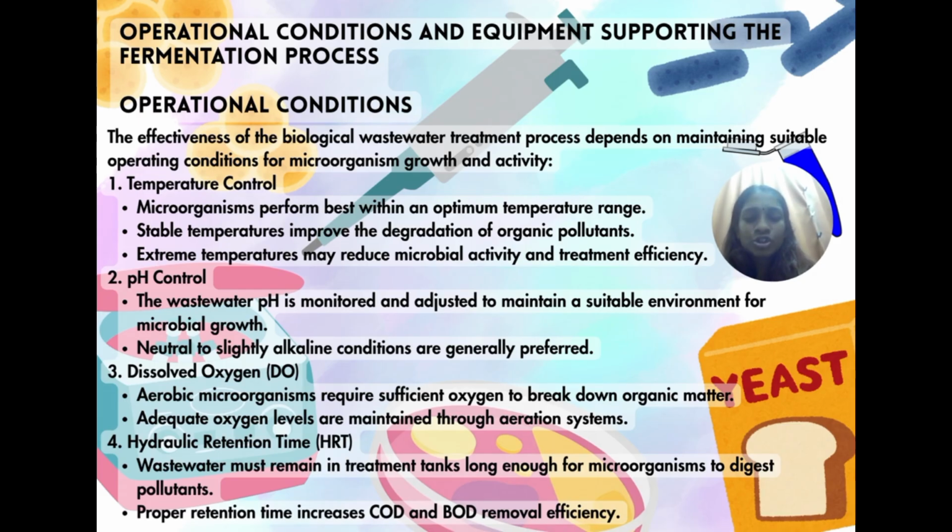For the temperature control, the microorganisms will perform best within an optimal temperature range. Then the stable temperature improves the degradation of organic pollutants. Next, for the pH control, the wastewater pH is monitored and adjusted to maintain a suitable environment for microbial growth. Third, the dissolved oxygen. Aerobic microorganisms require sufficient oxygen to break down organic matter. Lastly, for the hydraulic retention time, wastewater must remain in treatment tanks long enough for microorganisms to digest pollutants.